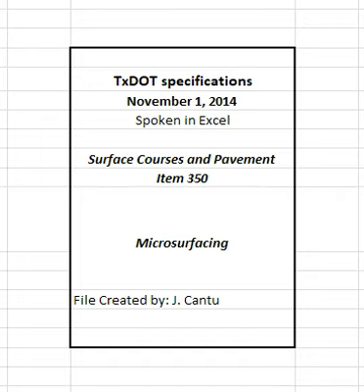Table 5. Operational tolerances. See table in specifications. 1. Dry to constant weight at 230 degrees Fahrenheit plus or minus 10 degrees F. 2. Material passing number 200 sieve including the mineral filler must conform to the limitations of the master gradation shown in Table 1. The asphalt content may be reduced below the tolerance when lean mixes are necessary for scratch and rut passes but not less than the design minimum shown for the wet track abrasion test when approved.